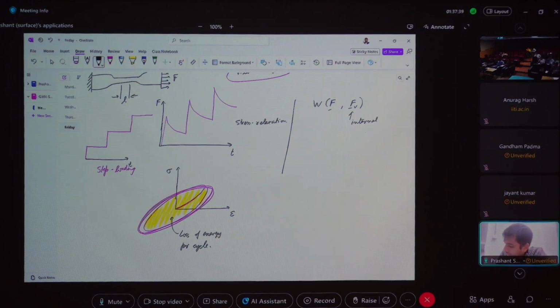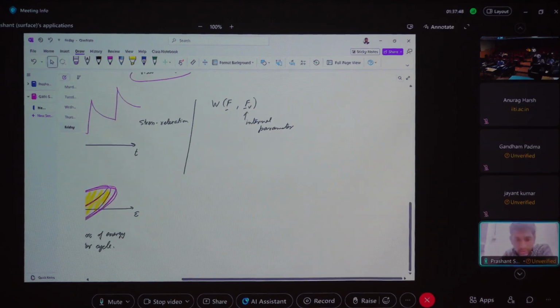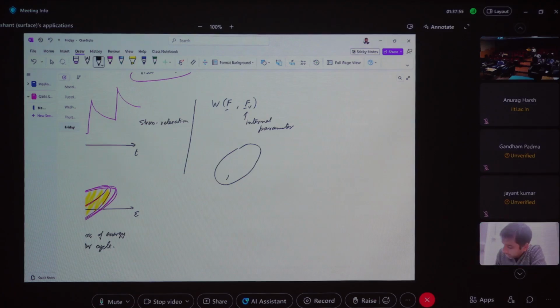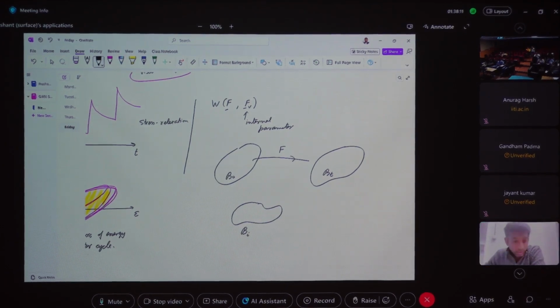So I'm not going to go into too much detail of how you do the modeling. I simply am going to show you a quick overview of viscoelasticity, and then you can see the relevant references. So remember, we had this reference configuration and a deformed configuration linked by an F. In viscoelasticity, what we say is, okay, let's take up an imaginary deformation. This is an imaginary configuration, Pi.